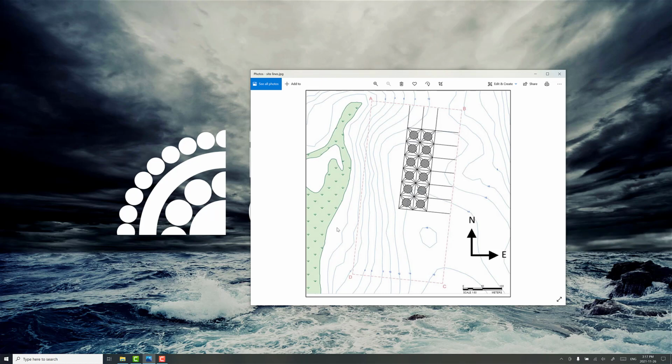Today I want to talk about generating a custom bathymetry mesh using chart data and an image you may have of a particular offshore or coastal site. It's pretty typical to have chart data or a schematic of an offshore or coastal location. This happens to be an example of a fish farm, and you can see we have some depth contours showing depth in meters, also typically showing a northing and easting direction. So how do we turn this into a custom polygon mesh that we can use for analysis in ProteusDS?